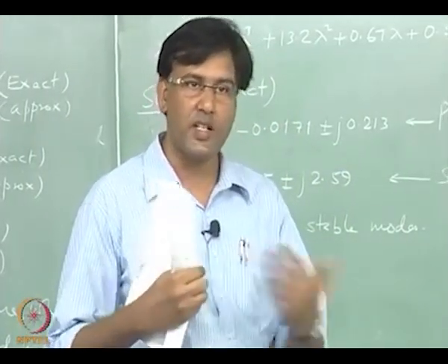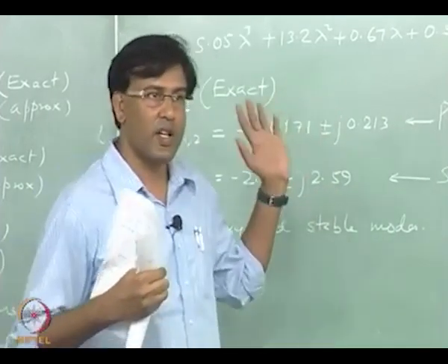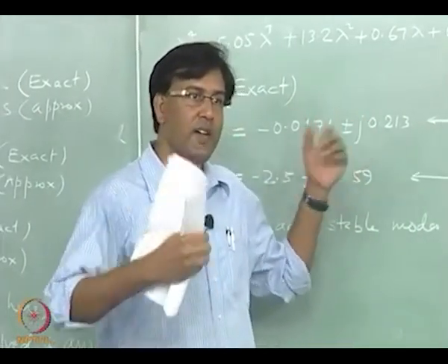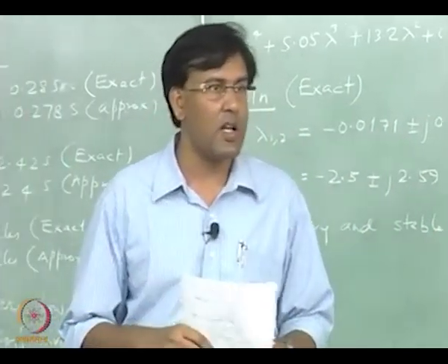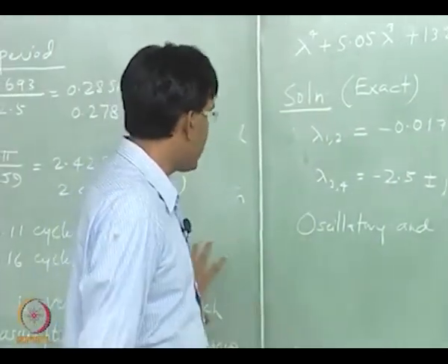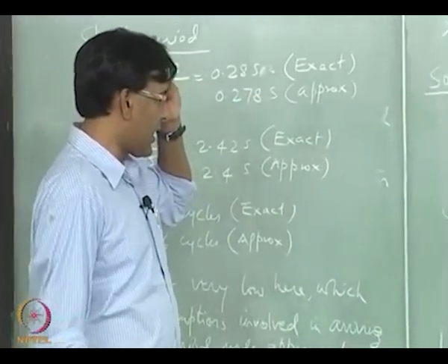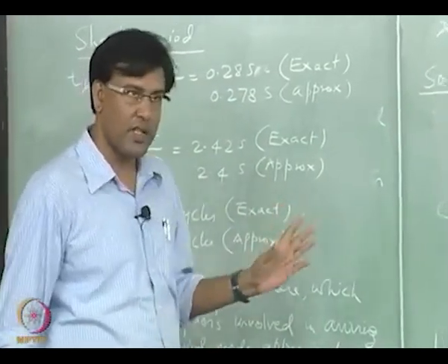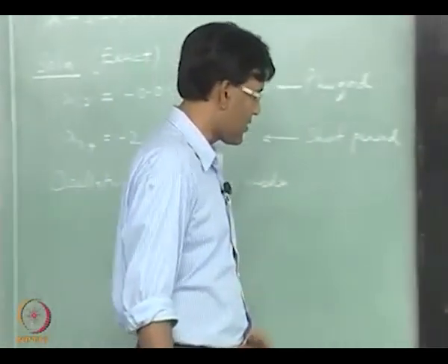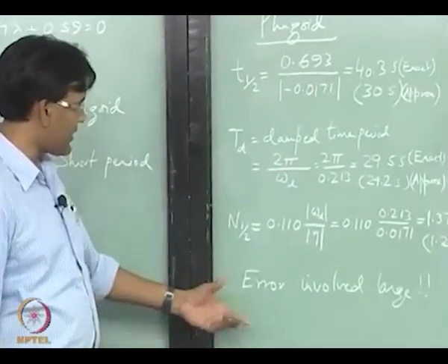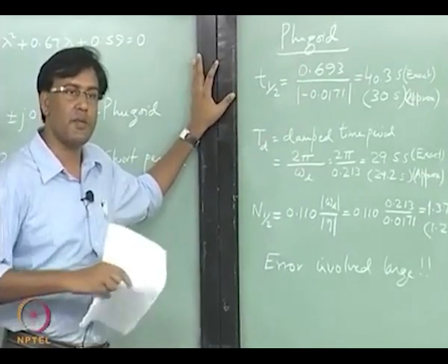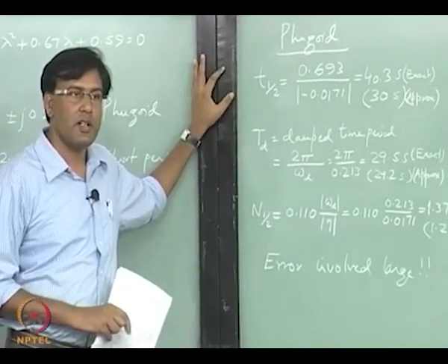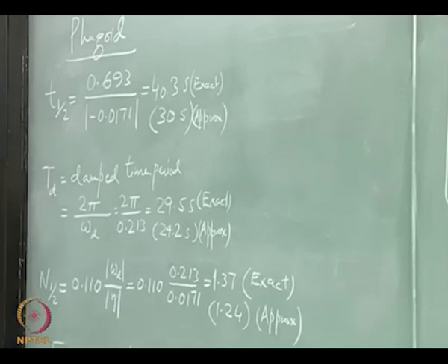To start with, we assume that they are decoupled based on the location of the corresponding eigenvalues in the complex plane, and then we started looking at simpler models. So there are arguments based on that. What people have come down to is that the phugoid mode is actually an ensuing motion. It comes from the short period. So when the short period ends, then you have this motion starting.